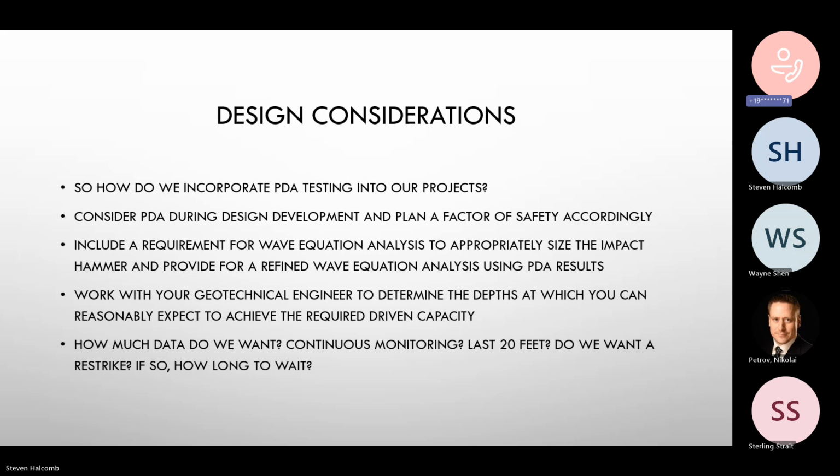Things also to consider, aside from just some initial planning, is to think about the wave equation and going through and doing a refined wave equation. If you've got a lot of piles, a refined wave equation comes in quite handy. You can do a little bit of PDA, and then you have inputs for your refined wave equation, and so you have a higher degree of certainty still using the wave equation, which is, again, way cheaper than even the PDA. So like Dave said, work with your geotechnical engineer to determine the depth at which you can reasonably expect to achieve the driven capacity.